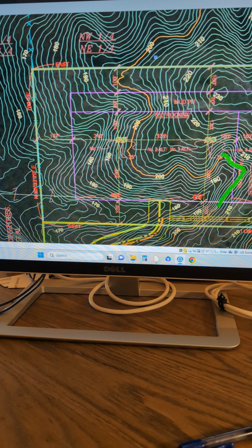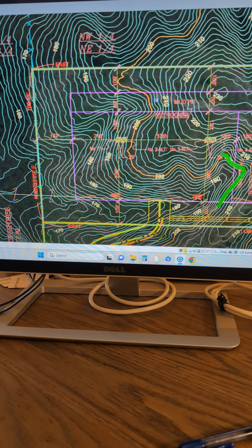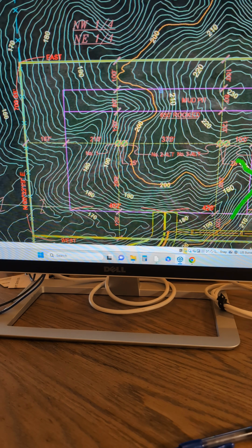Normally, I connect all the lines and then elevate later, to save time explaining how to do it. The purpose is you're gonna create all these elevated lines of existing contours, and then you're going to create the existing surface so that you can run your takeoff on your final drawing.